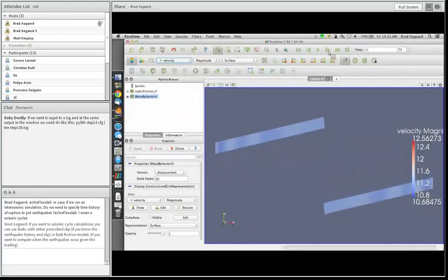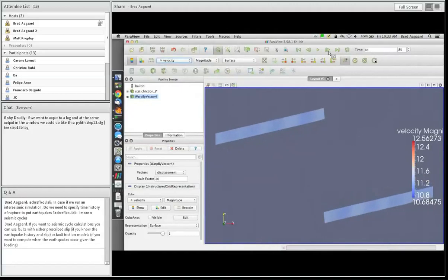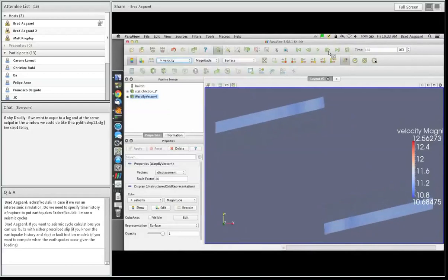And this is the steady state solution. When I impose a traction and cause slip greater than the friction threshold, I end up with the absorbing dampers opposing the deformation. There's an analytical solution for this: the traction I'm imposing is balanced by the friction coefficient as well as the strain within the bar and the stresses associated with that strain. That also has to be consistent with the stresses applied at the end of the bar being proportional to the velocity, and so we can solve for the velocity as a function of the difference between the tractions I've applied and my friction tractions.